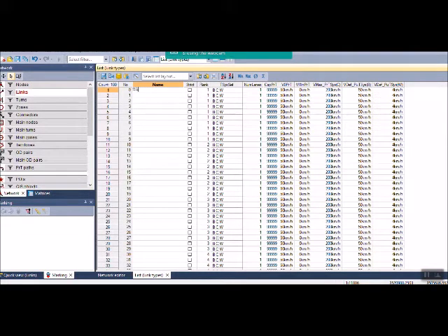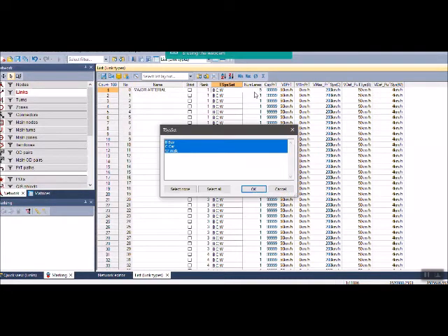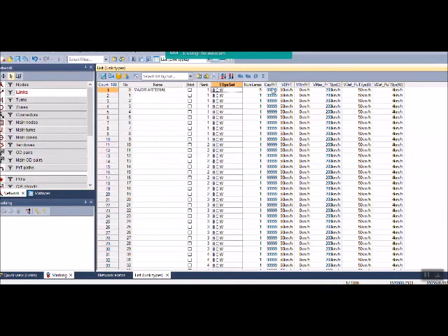So I'm going here to define my link types. Number 0 is the major arterial, and it has 5 lanes in each direction. Take care that this is the number of lanes in each direction, and it is used by all the modes, buses and cars and so on. And the capacity of one lane, you should search for this because it differs from one country to another and according to different researches.